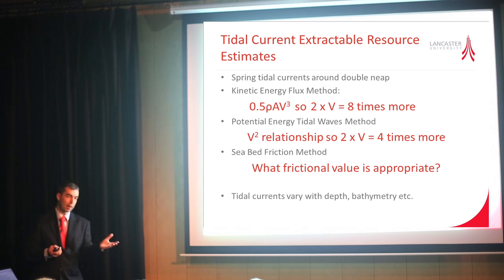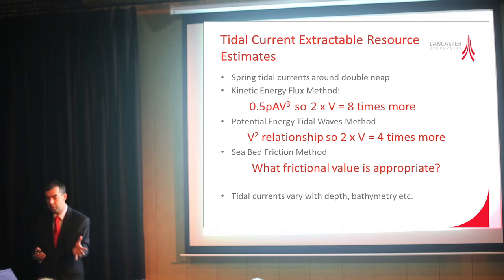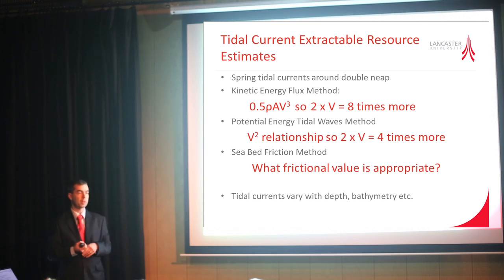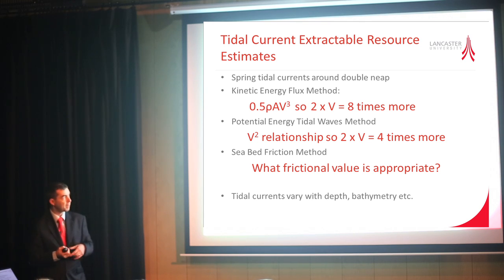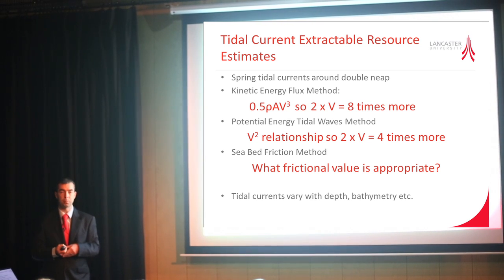Unfortunately, there's an alternative method of treating the tides as a tidal wave. The tide is a wave, it moves around in our oceans, it's just that it happens on such a time scale that we don't consider it to be a wave. But it goes up and down just like a wave, it's just that it takes several hours for it to go up and down and for us to realise that. And the wave is actually moving very fast, about 80 miles an hour, the wavefront moving around our coastline, so it is significant.